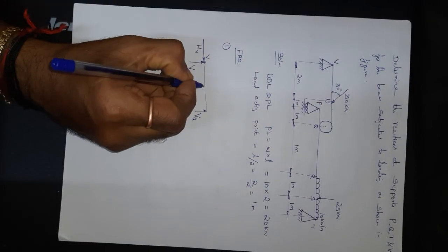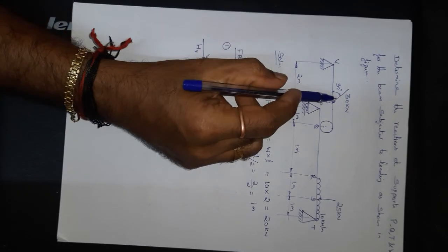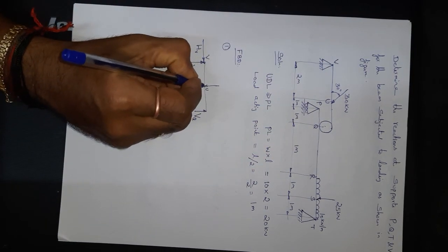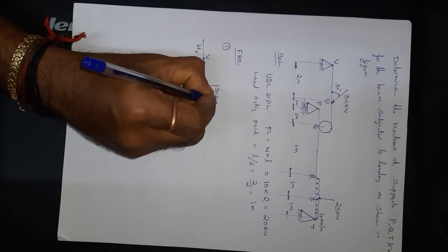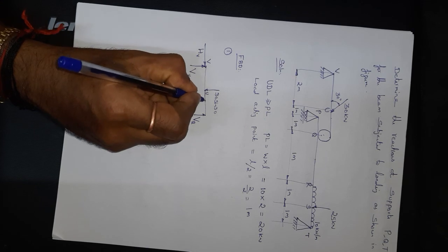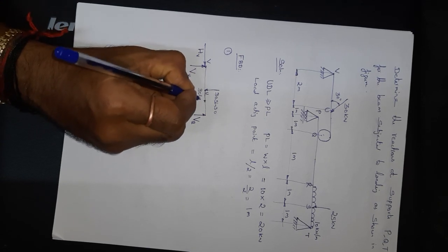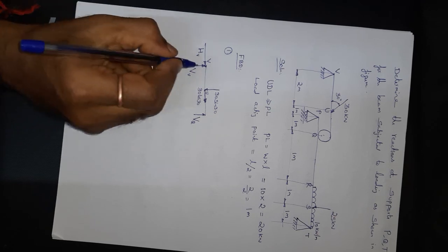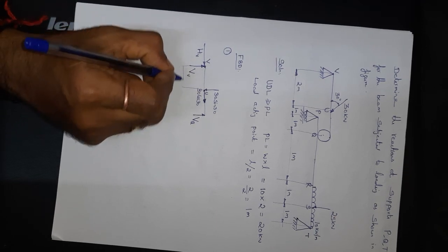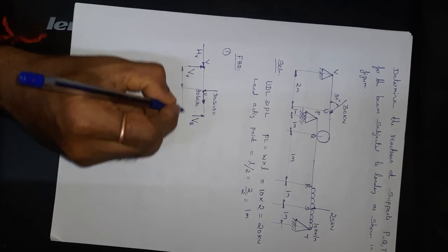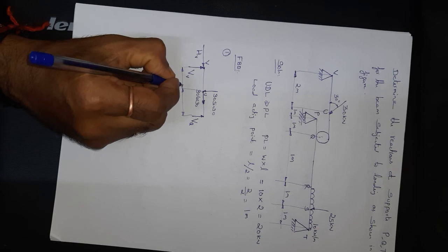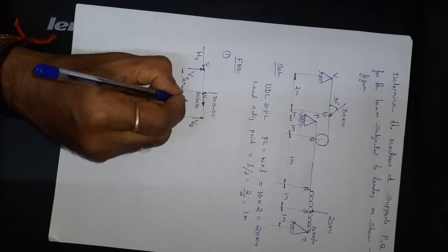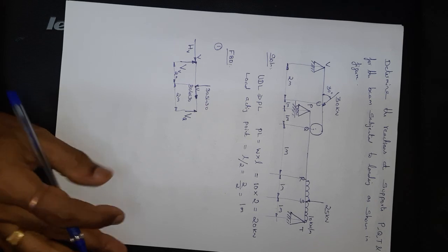The concentrated load which is acting at point U is inclined, right? So this needs to be converted into two components, the vertical component and the horizontal component. The vertical component can be 30 sine 30, and the horizontal can be mentioned as 30 cos 30. Got it? Now mention the distances. Distance between V and U is 2 meter, and from U to Q, which is 1 plus 1, is 2 meter, right? So now I have completed the FBD of 1.